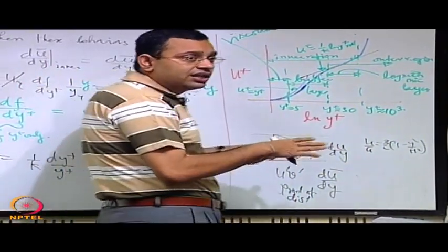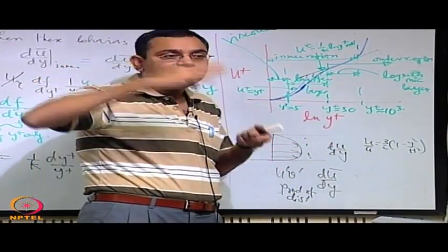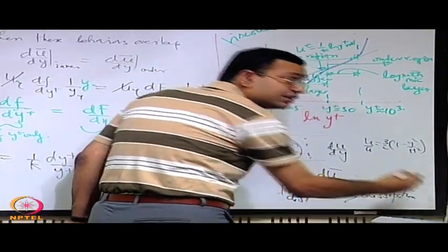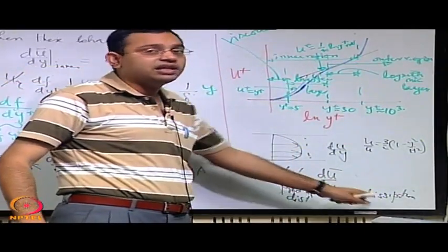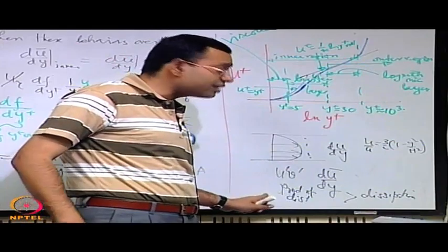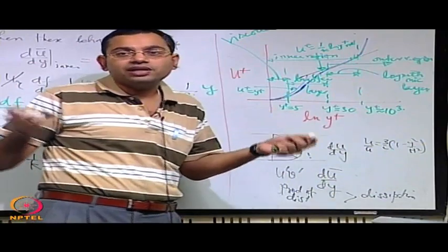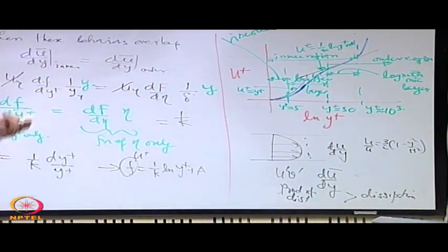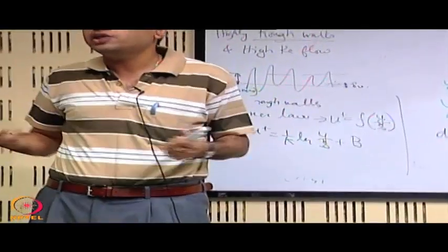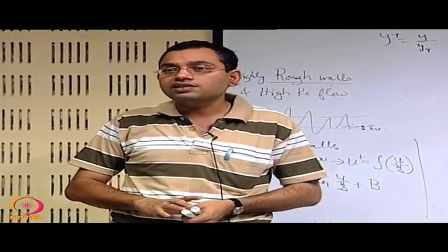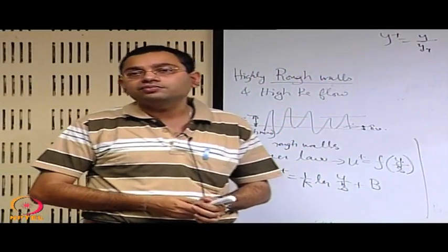So at the end the turbulent kinetic energy, or the fluctuation kinetic energy, will be more if the production becomes greater than the dissipation. Dissipation is also by viscosity. Without viscosity there is no such production and there is no such dissipation. With viscosity there is a production and there is a dissipation, and if the production is greater than the dissipation, then the fluctuation component kinetic energy will grow. That means viscosity actually destabilizes the situation. So that is what we have understood, that it may be a very non-intuitive situation where viscous effects may destabilize the flow rather than stabilizing it, and turbulence is one of the mechanisms that triggers it.